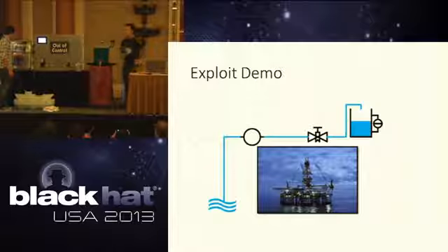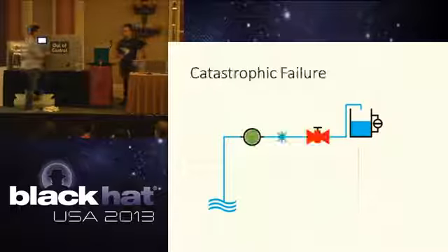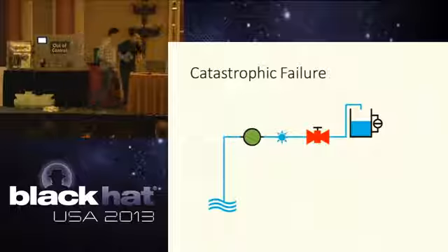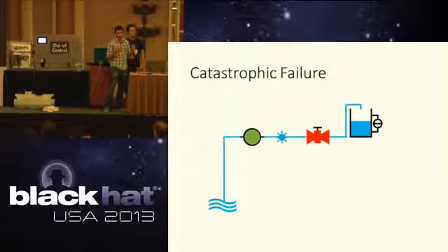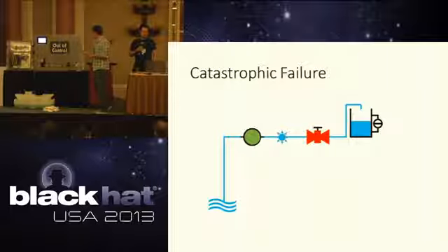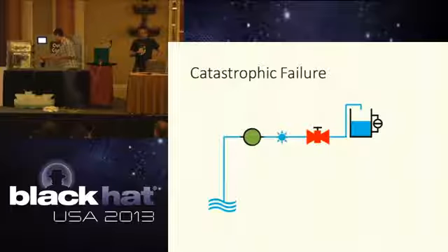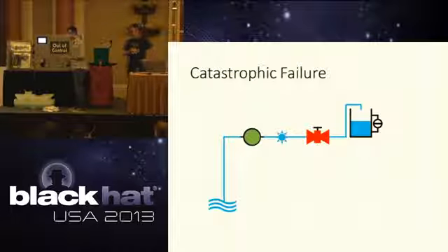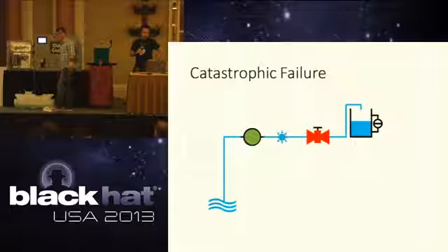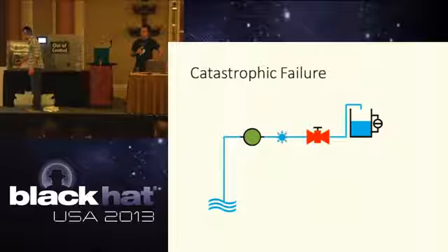But anyway, let's go over to the next slide quickly. We're able to do catastrophic failure on this. One of the things we were talking about is that we have safety interlocks and permissives on here that do not allow this pump to turn on if this valve is off. Well, it doesn't matter what the safety logic has. If you drive these output signals directly, you could be sending logic to turn off this pump all day.